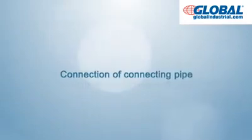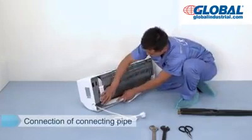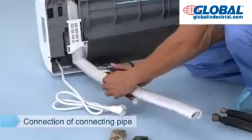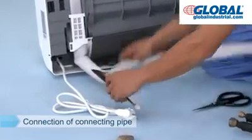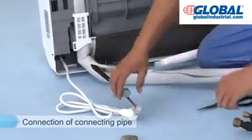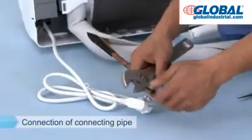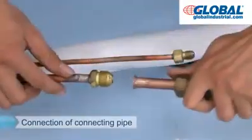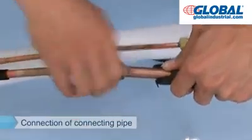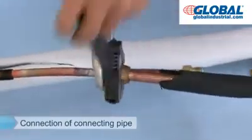Connection of connecting pipe. The input-output pipe should be adjusted to an appropriate position at slow speed with even strength. The insulating sleeve is cut 4 to 6 inches to facilitate the connection with the copper pipe, and check for damage and bend. Remove the nut cap of the copper pipe. The cone should be vertical to the top pipe socket. When the nut is near the bottom of the bolt, tighten it with a wrench. Loosen it moderately after tightening for further tightening.